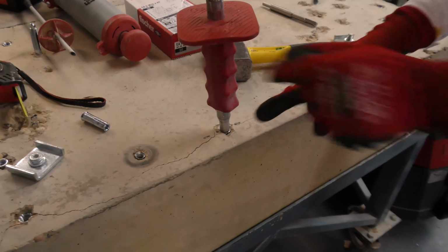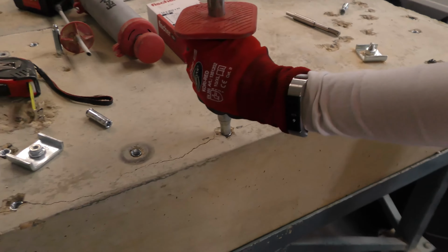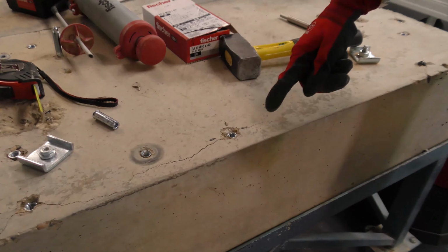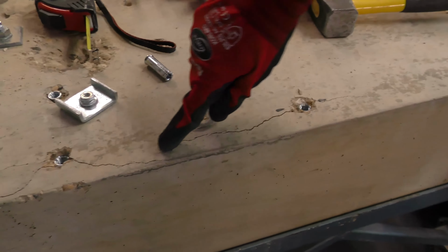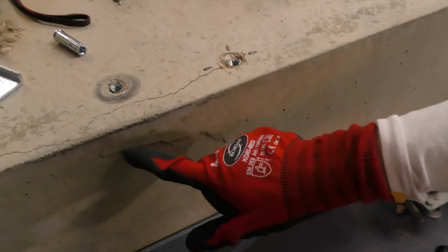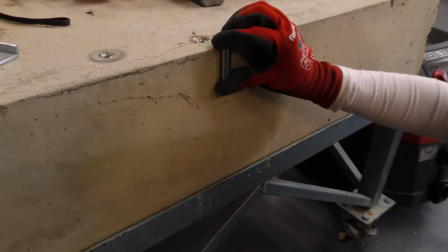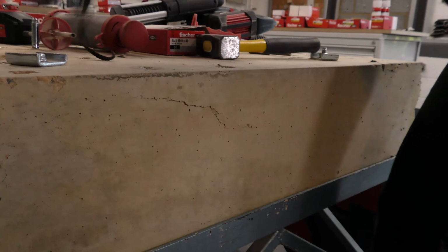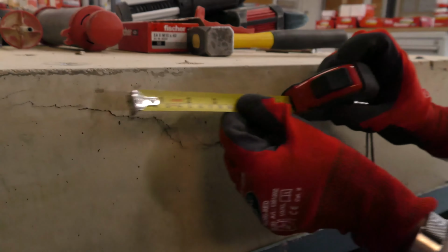You can see, fixing is not set fully and already big damage to the concrete. And you can see how far the stress travels, far away from the fixing. So a big part of the concrete is damaged. And you can see the crack going also further down, probably twice embedment depth, around 70 mil deep into concrete. 80 millimeter damage.